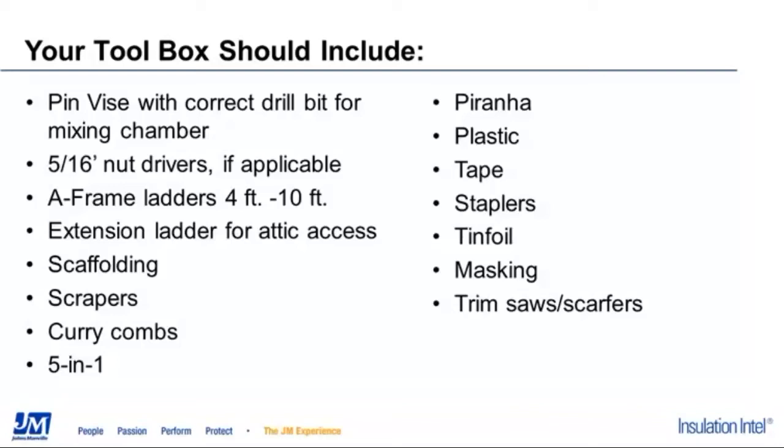Curry combs, if you guys aren't aware and you don't have a horsehair brush on your spray foam truck, you ought to run to your local farm supply and get one. Curry combs are super, super common for removing the overspray off the face of studs. They're a great tool to have.